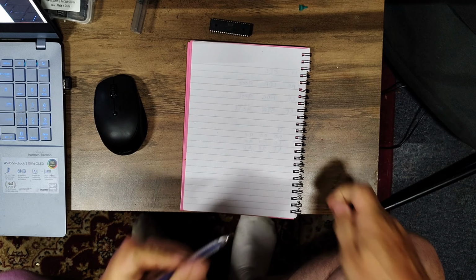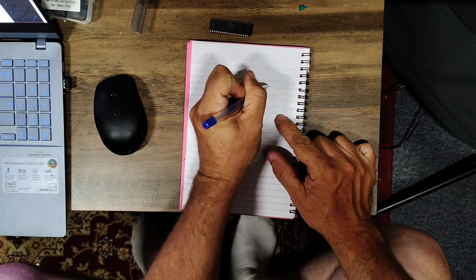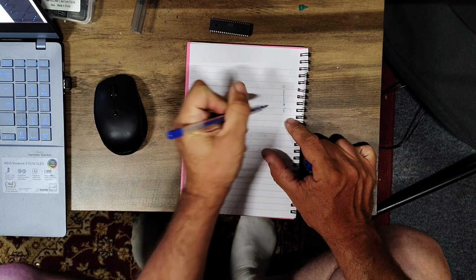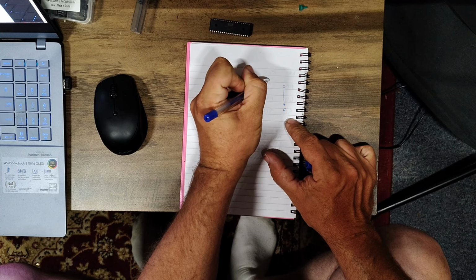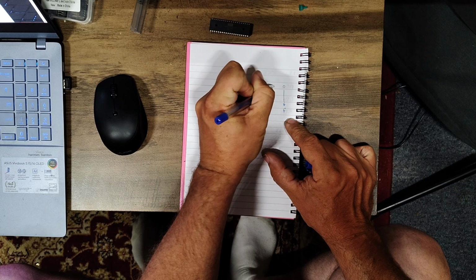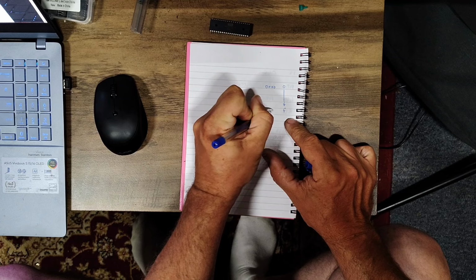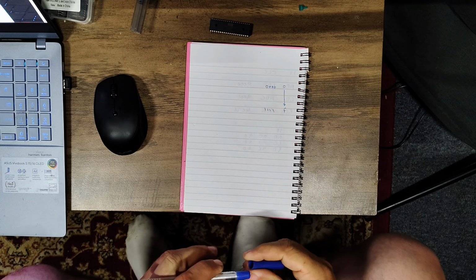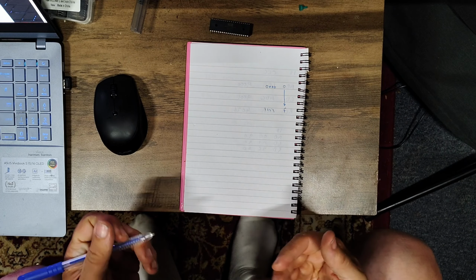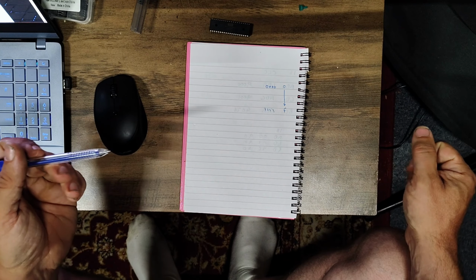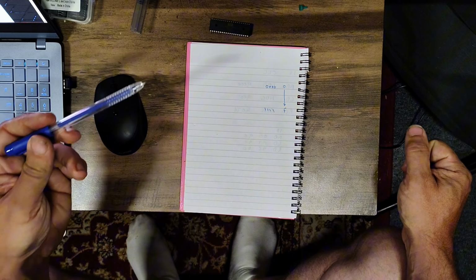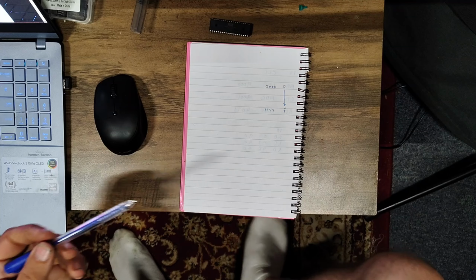Okay, so we want to write through to 0 through F, which is going to be 0000 through 1111. But we've got to have a whole bunch of other addresses to write to. Now, on our particular computer, if you remember, the addresses 8000 through FFFF are already taken up by the ROM, so we can't use those.